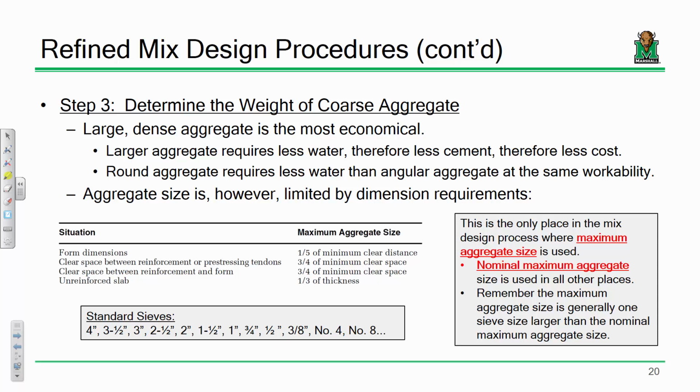When you do reinforced concrete design, one of the key aspects that you have to assess for a given design is what are called cover requirements. Okay? And cover is essentially the space between the edge of your, let's say, column or beam, or the formwork, if you want to look at that, between the edge of the formwork and the edge of your rebar. Okay? And different applications are going to have different cover requirements.